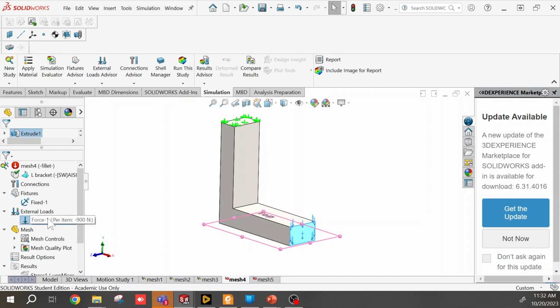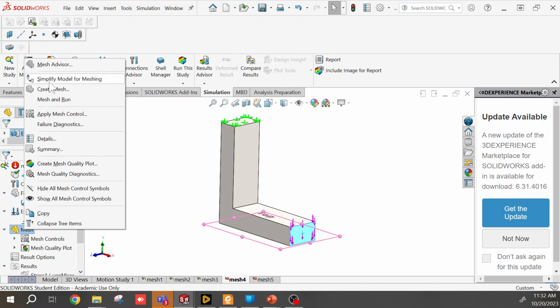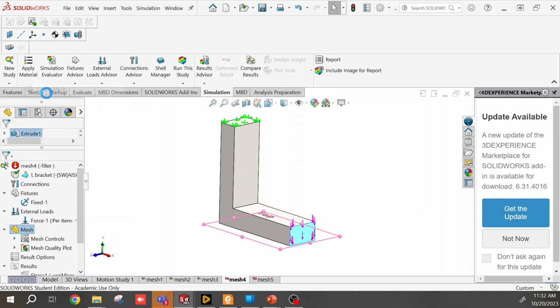If you fix it at the top of that face and put the load down there, it's just going to try and bend that thing. It's not like it's going to buckle to the side or anything weird like that. So it should converge and run like this. And for our mesh, once again, we right click on the mesh here. We click create mesh.